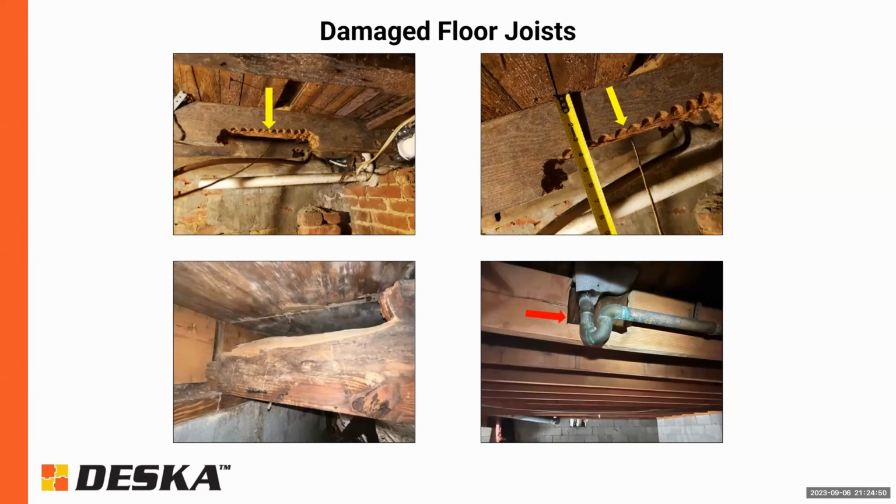obviously are major issues. If it's just one joist, it's not catastrophic, of course, as there's many joists, but it is definitely a structural issue and it needs to be repaired. If there are numerous joists notched like this, that can become a very serious issue.